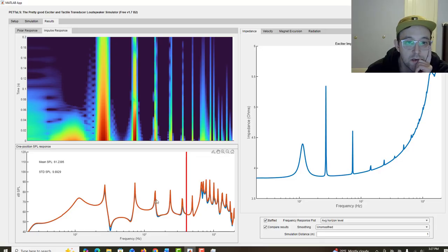Okay, so with the higher Q, a Q of 200, we do see sharper peaks in the frequency response, although not that much sharper, and that could be because of the frequency resolution, or it could just be because there's a limit to how sharp. You aren't going to get infinite dB if you keep setting the Q higher and higher. There's a limit to that.